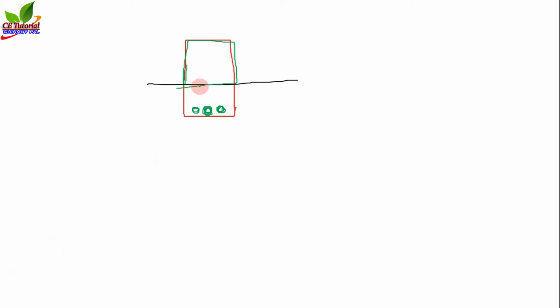When we place the reinforcement at the tension zone, you have to place the reinforcement where the maximum tensile stress is producing. Okay, so this is the bending stress diagram, and all those stress will be taken by concrete, and tension is at the bottommost fiber, the maximum tension is there.